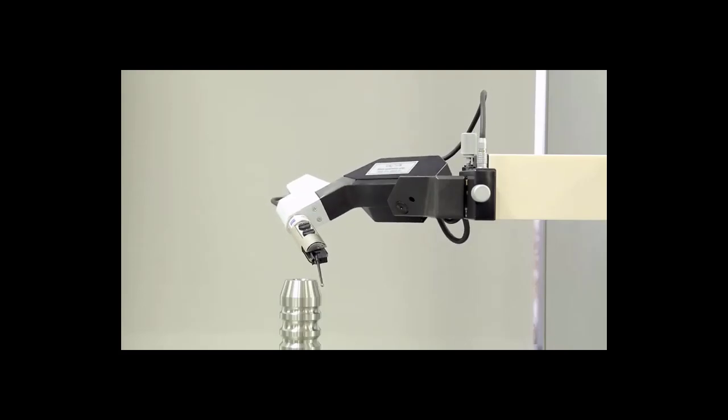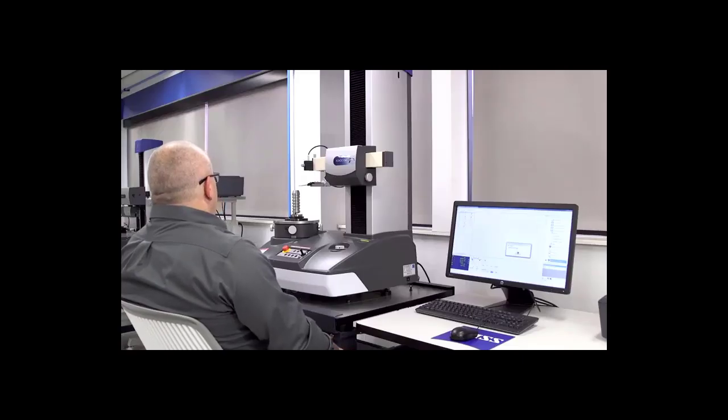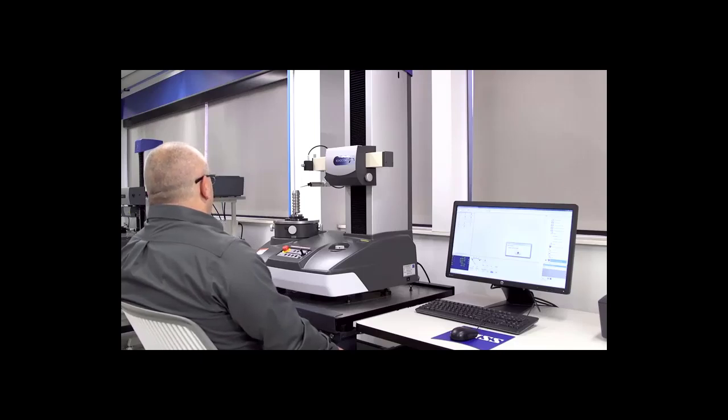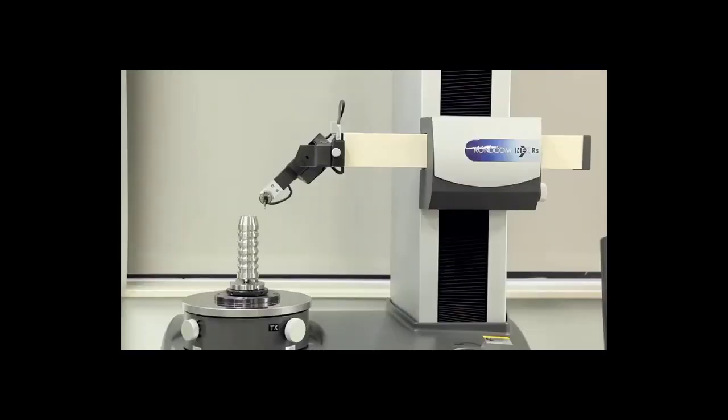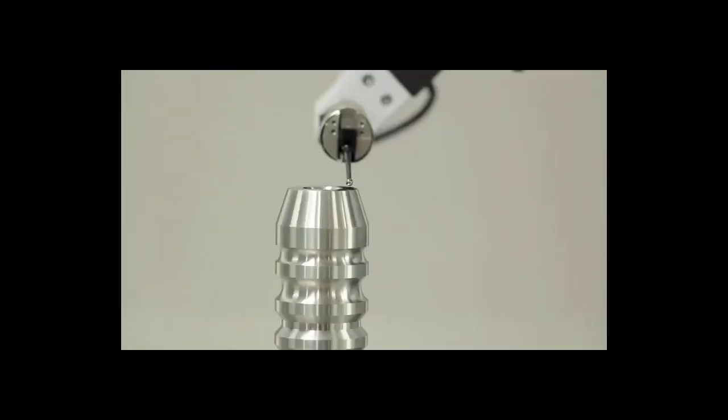From here you can see that we are able to rotate and choose a range of degrees, keeping the stylus normal to the surface. With the CNC motorized head, we're also able to measure ID, OD, upper face, and lower face. So even if you only have a couple of directions, this may be a great solution for you, where your operator does not have to come back and change the direction of a probe in order to complete a measurement. It is fully programmable for multiple directions, even if it is only one or two. That way there is less operator interference and quicker measuring cycle times.